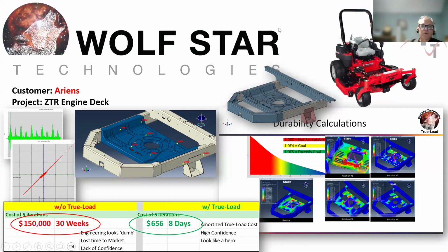But basically, with our TrueLoad software, we were able to come in and say, "Hey, lay these 8 strain gauges here on your structure." And then on the left here, you can see the time histories of strains and simulated strains in the background. And here's one of our standard cross plots. We're plotting measured strain versus simulated strain for all of the strain gauges for all time on the plot. And we've got this nice 1-to-1 strain correlation here. You know, this is one of the things that customers get.